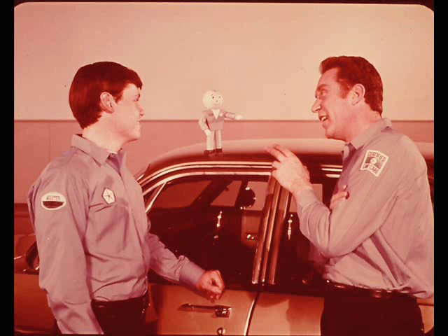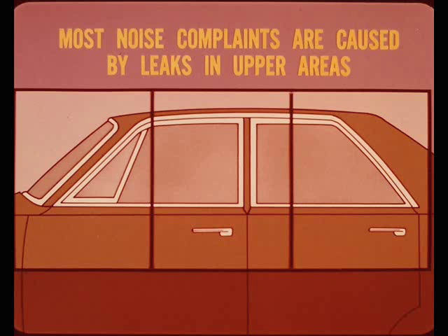Al, before you start noise detecting, you'd better tell Harry why the upper areas of the car are the most critical. Hiya, Tech. A good point. It's simple, Harry. Noises at ear level are more disturbing, and this is the area where outside and inside pressures differ the most, mainly for these reasons. Most wind noise complaints are caused by leaks in the upper areas of the car sides, down to about a foot below the belt line or around the windshield. Leaks lower down can cause drafts, but they seldom cause wind noises.